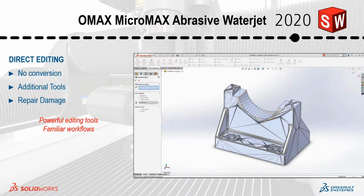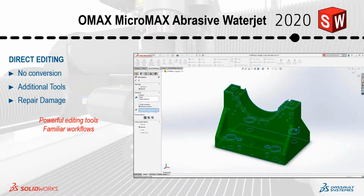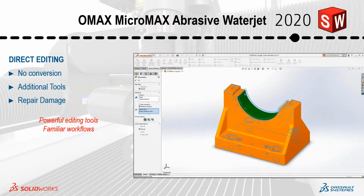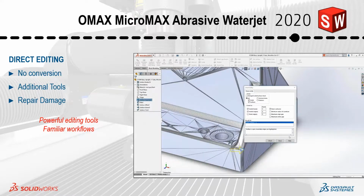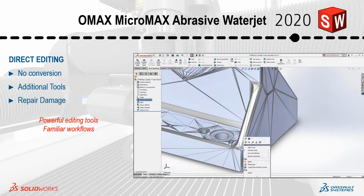It is not uncommon to have damaged surfaces when importing mesh geometry as well. So using geometry check, you can quickly scan for open surfaces. As you can see in this video, very quickly we're trying to look for those unwanted holes, something that we do not see with our naked eye.